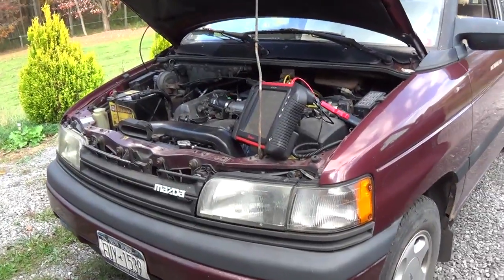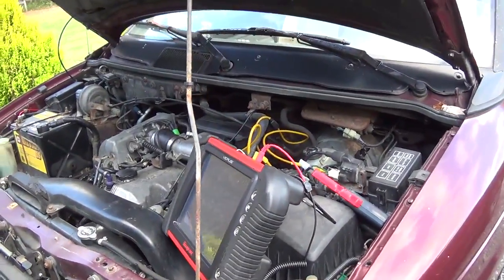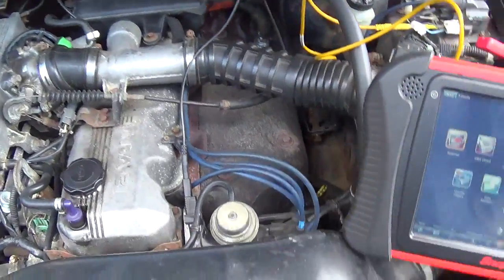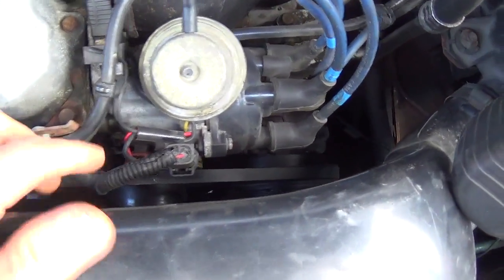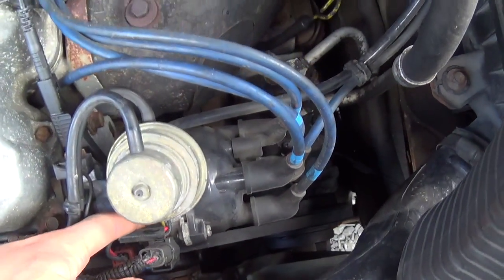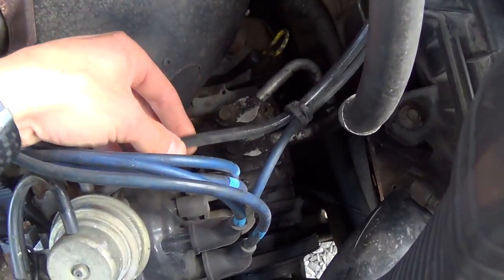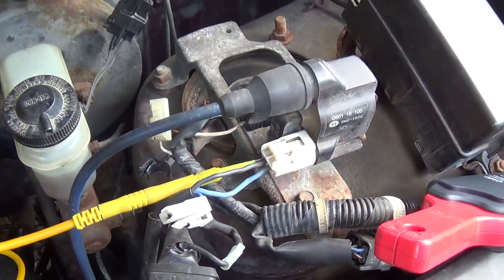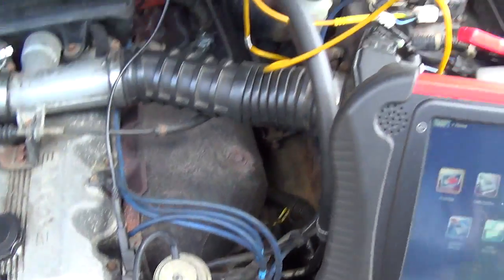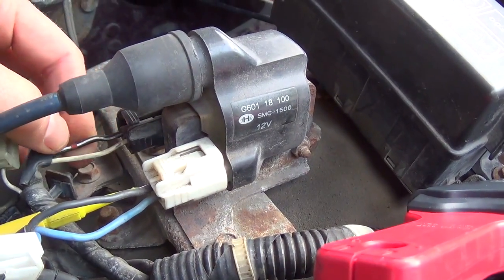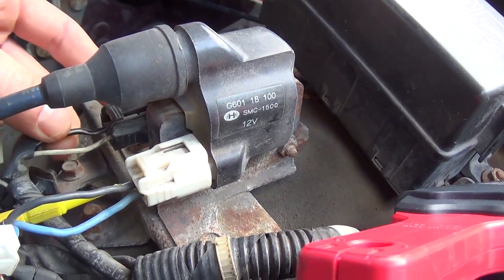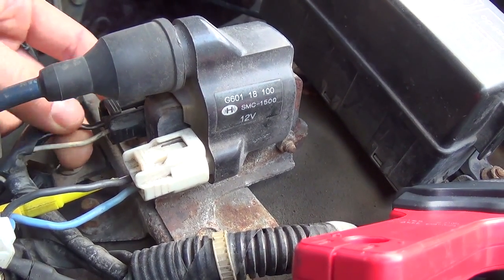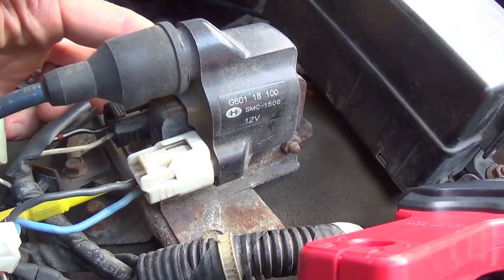So now what we want to do is measure the power consumption of the ICM that lives inside the distributor here. So here's a setup. There's a distributor, obviously. The ignition control module lives inside of here. Here are the wires coming to it from the ignition coil. Pretty straightforward. Now the wires in the ignition coil, there are four wires plus the high tension lead. So this black with a white tracer, that is the main feed from a fuse. Now that feeds the primary winding in the coil.